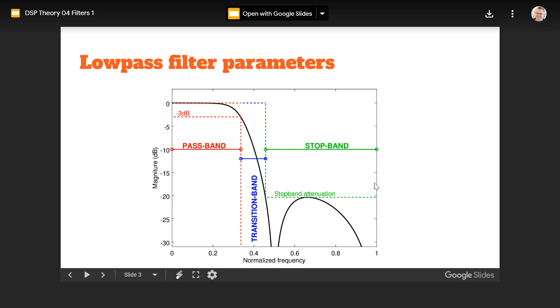Similarly to passband, it's defined by the -3 dB point or some other point here. So there is always a corner that defines it for passband, and also a corner that defines it on the stop band. So you should think of a filter response as a box.